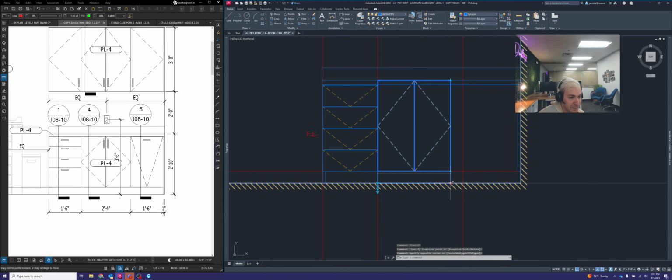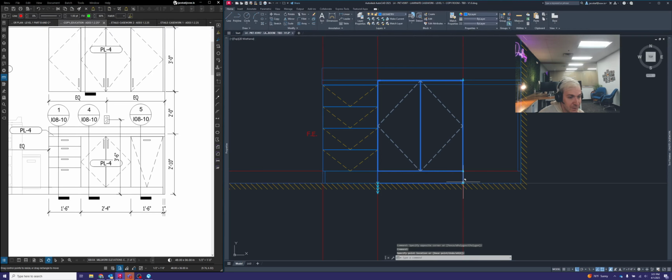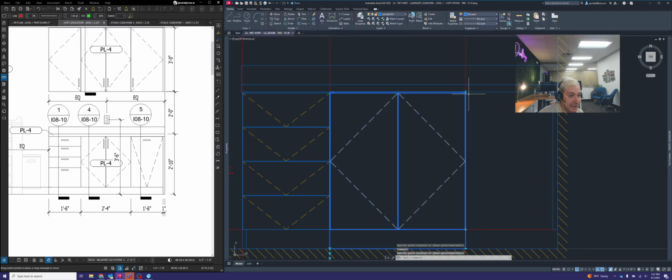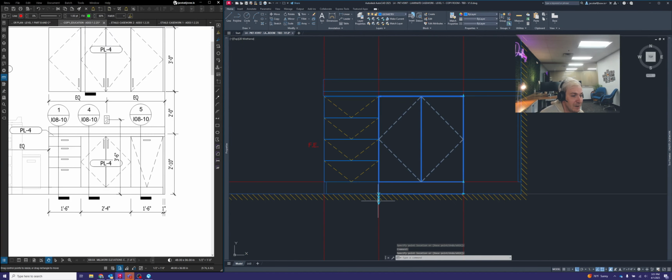Got to do a little bit of fine tuning. We're going to move this over so that it sort of fits into our grid. Slide this down. That way it sits below the countertop. And then we need to toggle on the one shelf option. Okay. No finished ends, no fillers for this cabinet. So we are good with what we've got.